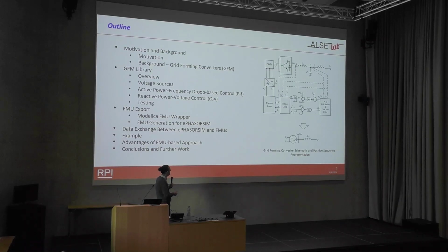Before I go into details, in my field, in the power grid field and power electronics too, there's been all this hype about grid-forming converters. This would be the picture of the converter. It's something called a modular multilevel converter versus voltage source converters. Basically, if you control them in a certain way, you can reproduce the sinusoid that you have to inject in the network, and it has a little bit more controllability.